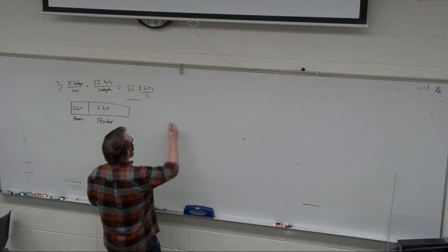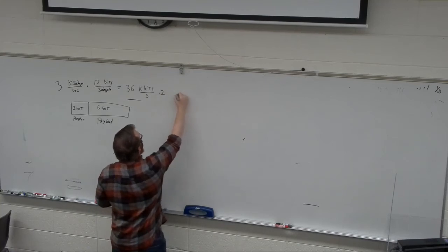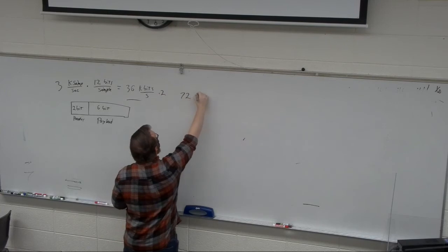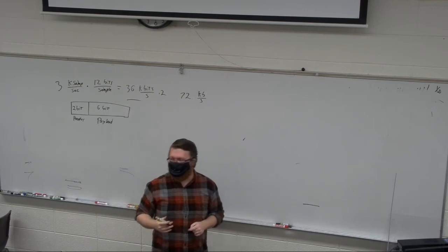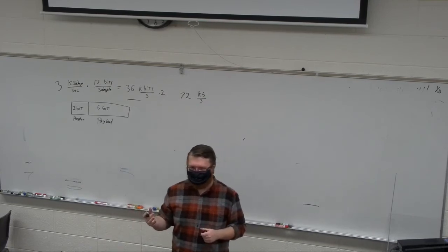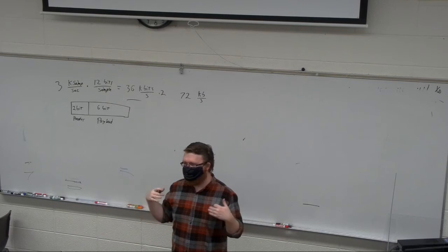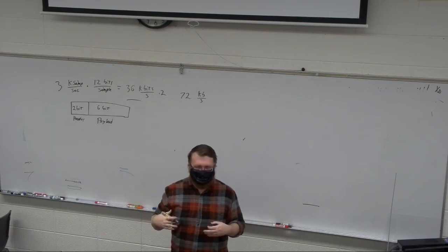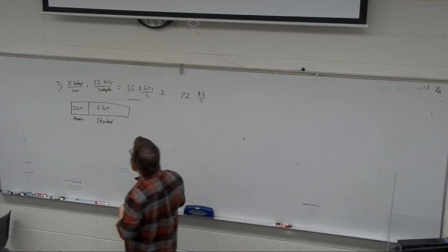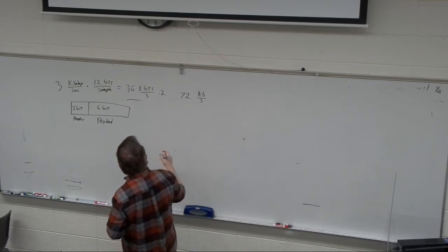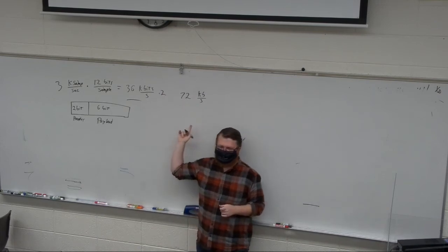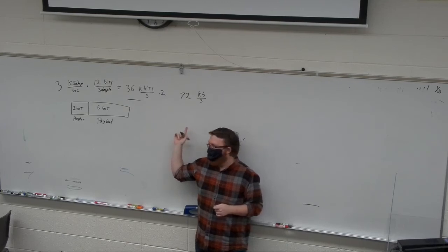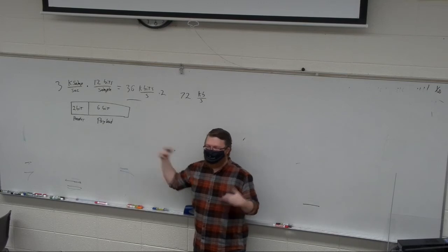So if this ends up at 72 kilobits a second, and we're sending our UART out at 115 kilobits per second, everything's fine, right? We're transmitting out faster than we're getting new data. But I'm going to switch that around on you, and I'm going to limit your UART to 50K. I can't remember the exact number. It's like 56 something. So that way we're going to get a backlog of data that needs to be handled.